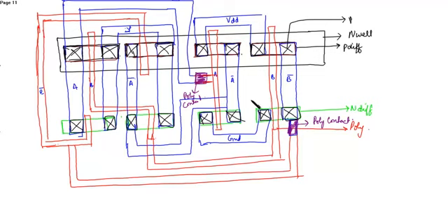And after placing the diffusion contacts, next you have to place the substrate contacts, and the substrate contacts are placed in VDD and ground. So you can place one over here, similarly one over here. Okay.